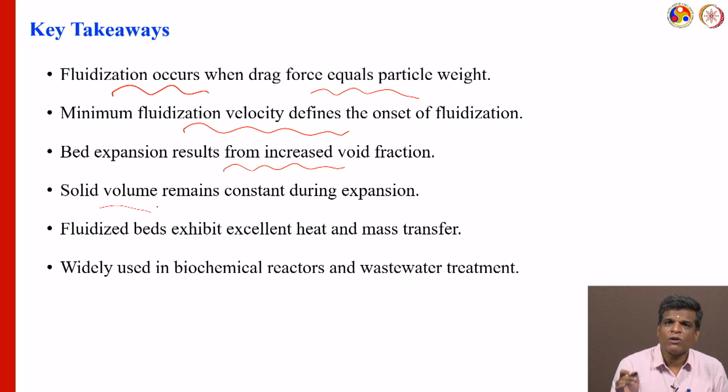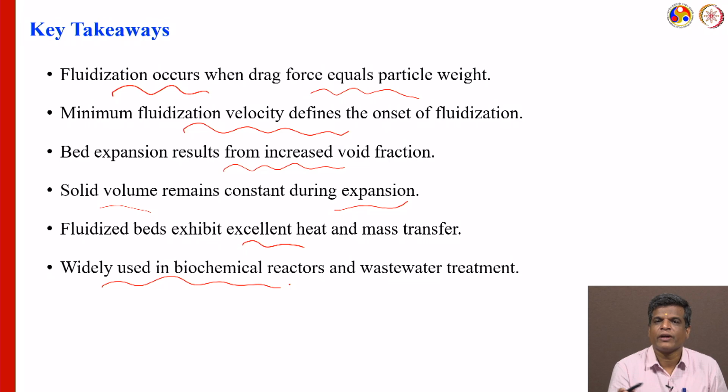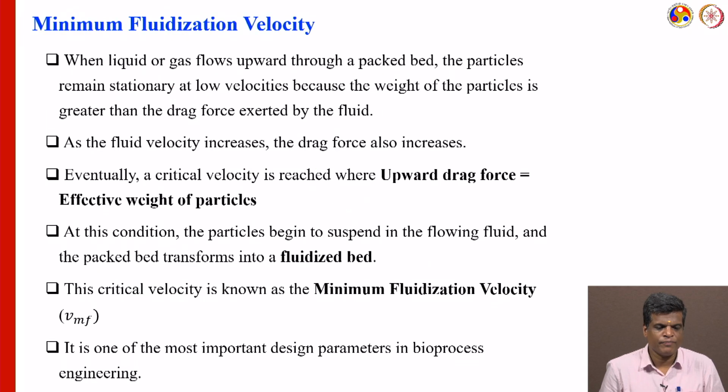That the solid volume remains constant is very important. Whatever the solid volume is, it remains constant, while the bed gets expanded during the expansion. So, a fluidized bed exhibits excellent heat and mass transfer compared to a packed bed. So, it is definitely very useful for biochemical reactors and wastewater treatment processes; the fluidized bed is very important. These are the key takeaways here.